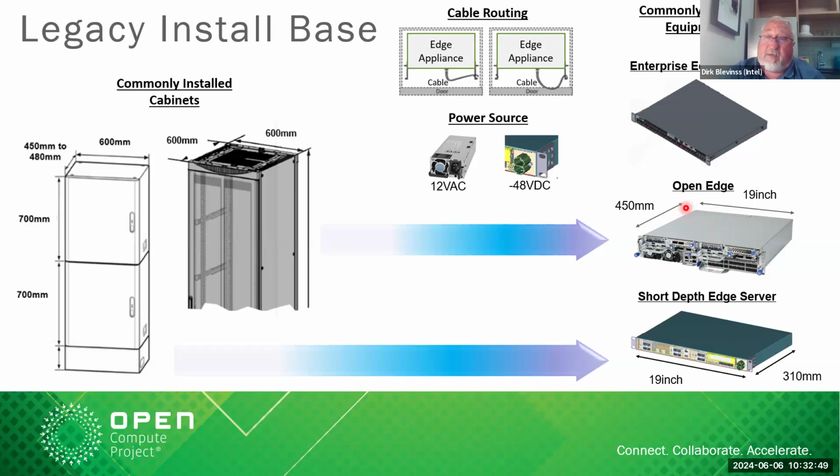But those chassis were traditionally designed for side-to-side airflow versus front-to-rear airflow. Because of that, it starts to play into the cable bend radius and what the requirements are there. What people have traditionally been doing is going as deep as 450 and then taking this extra 150 that exists here, coming off the back wall approximately 30 millimeters, eating into this cable bend radius location, and then allowing front-to-back airflow to occur with essentially a plenum in the back to be able to escape the air in the solution.